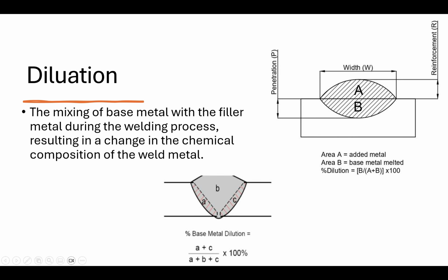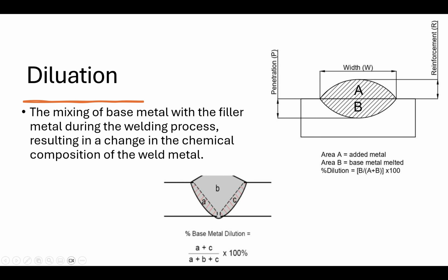And stainless steel has got maximum 0.08%. So from the carbon steel side, carbon is coming into the weld pool. And here again, SS316 will not contribute much because it has got low percentage of carbon anyway. So this deposit will have different chemistry than the original that comes from the electrode as well as the individual base.